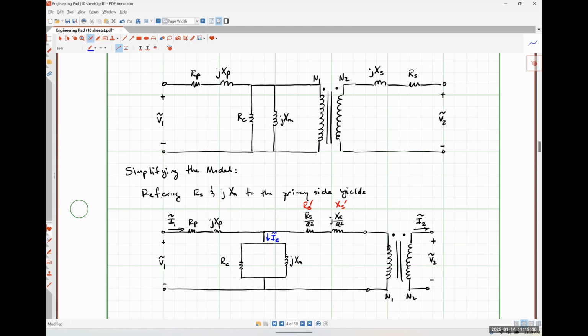So the excitation current is a current that is added to the primary current. If we're looking at this from a Kirchhoff's current law perspective, we have the excitation current and the primary current combined together to establish a flux around our system.